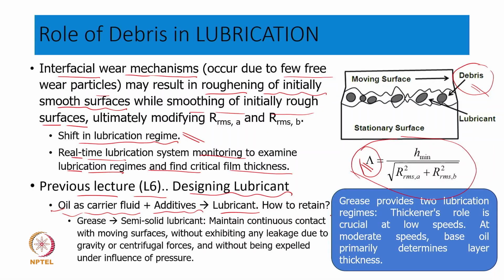The question comes, how will I maintain, how will I retain the lubrication layer on, say, this kind of surface? How do I retain this lubrication layer? And that's where a new kind of lubricant which has been studied extensively in the past is grease lubrication. We say it is not a solid, it's not a liquid. That's why we are using the word semi-solid lubricant. And in my view, semi-solid lubricant having controllable properties will be very useful for us.